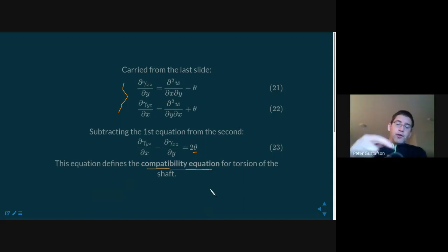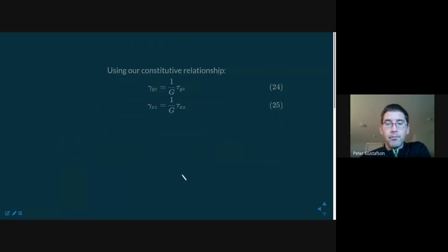However, if these 2 points up here, at the other end, the opposite end of the split, cannot form a new crack, or we've changed the problem, right? So this equation essentially says that deformation needs to be compatible. You can't form new cracks or voids. You need to have single-valued displacement functions.